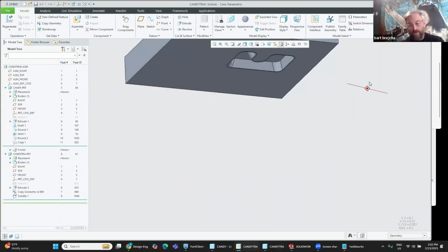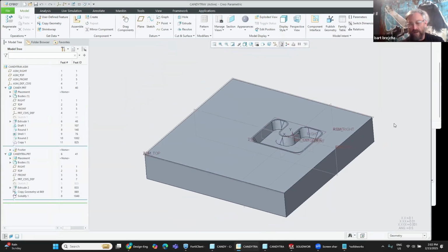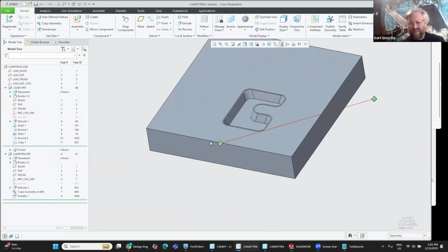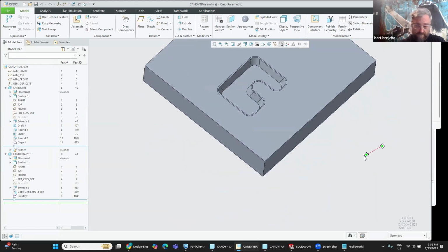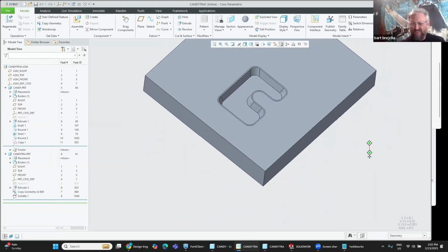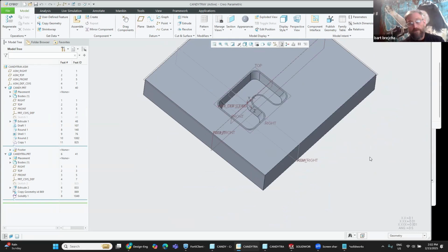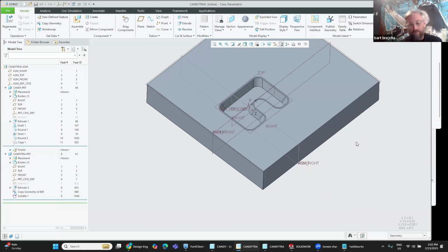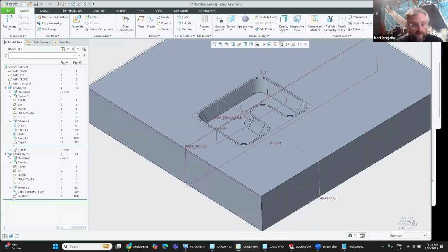So two things: publish keeps the geometry nimble. In SolidWorks, if you do a wiring harness and you need some geometry in your harness to route around, you take the entire aircraft. That's a bit aggressive. In Creo, I just pick some of the surfaces near the fuel tank because I know I'm routing wires down the wing. So it's very, very different to think about. You know, so I can hide that copy.